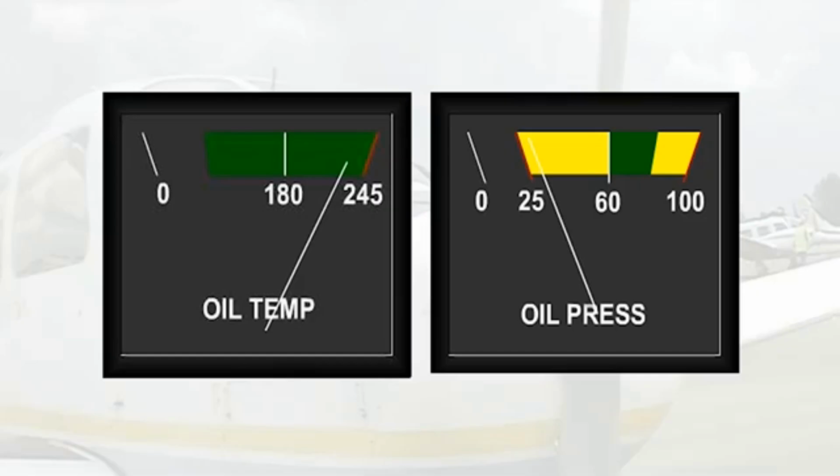Alternatively, if oil cooler shutters are not an option open to you, then consider either reducing engine power, or lowering the nose to increase airspeed, or even making the mixture richer. Any or all of these actions can be used to cool the engine and thus cool the oil, bringing its viscosity back up to the point where the system can cope. Once again, though, if the minimum oil pressure cannot be maintained, then the engine must be stopped to prevent damage.